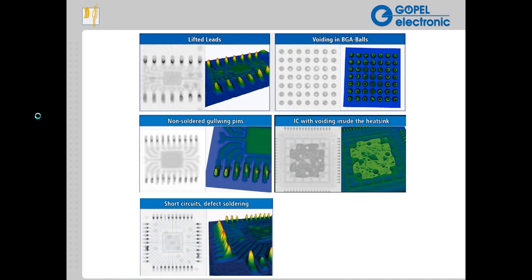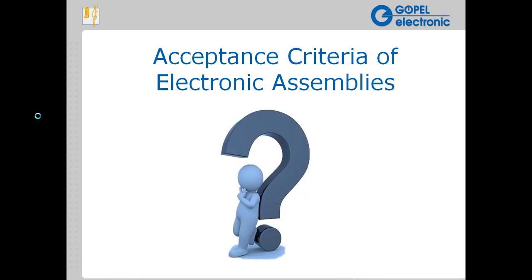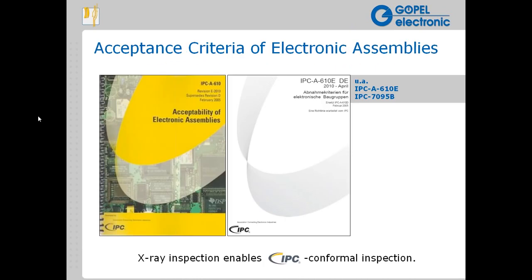A secondary criteria for inspection here is actually the forward meniscus of the solder joint. That is visible, of course, in AOI in a number of ways. It's also visible in AXI. But much more challenging in most cases is the primary criteria, which is often only visible to AXI. Under certain circumstances, we can visualize that solder aspect with an angle view, an AOI angle view, but it's much more effective in AXI. You can see the profile of the heel much more clearly, the density of the solder,